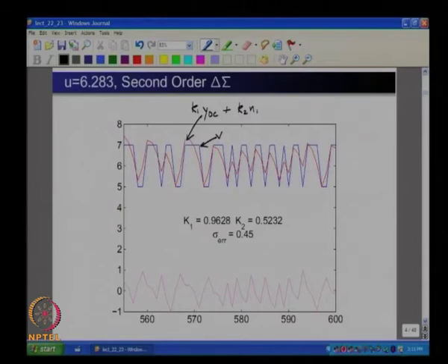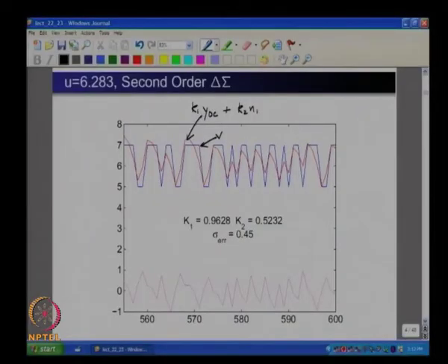and since we are now saturating the quantizer, it makes sense that we are not able to fit this quite as nicely as we were able to in that region where the staircase had a gain of 1 for both the noise and the DC component, and that does come out in the math.